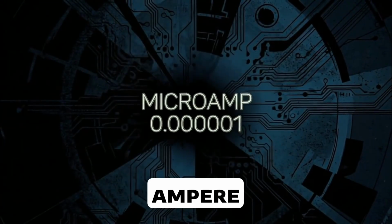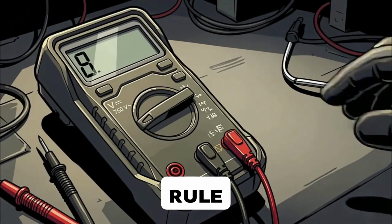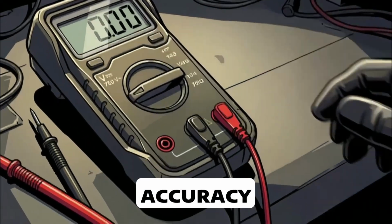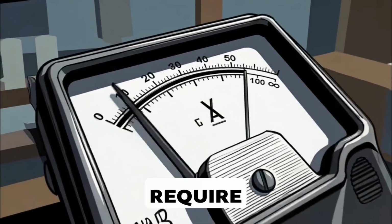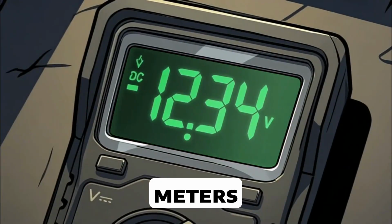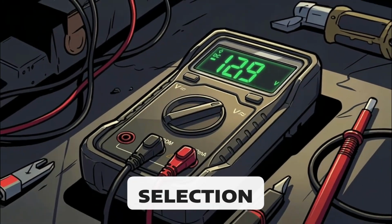0.000001 Ampere equals 10 to the power of -6. Important rule: start on the highest range, then work down for safety and accuracy. Analog meters require correct scale reading and multiplier use. Digital meters are easier to read, but still need correct jack and function selection.